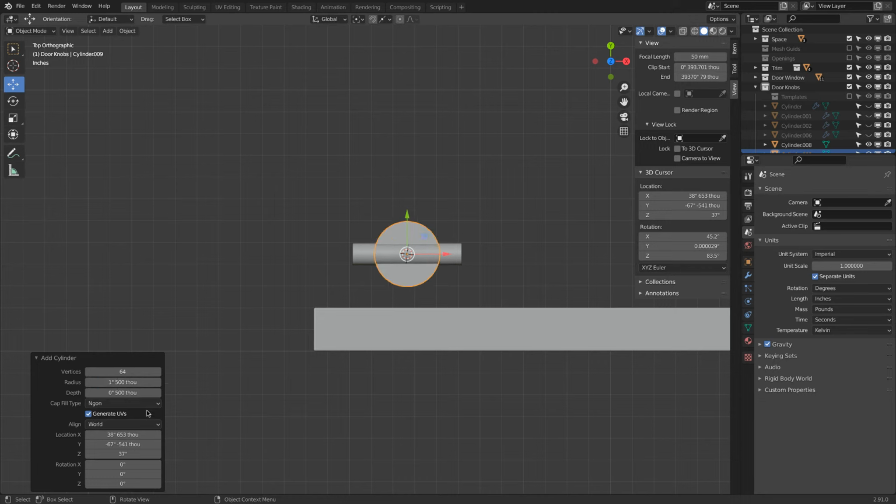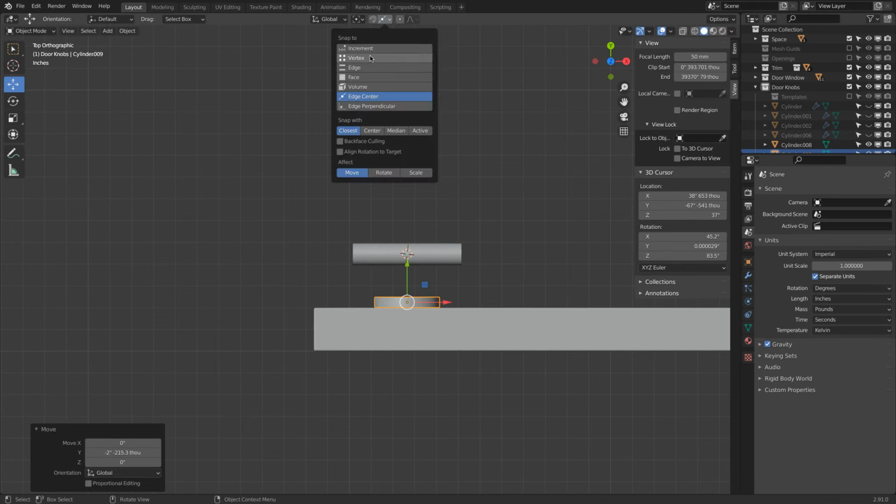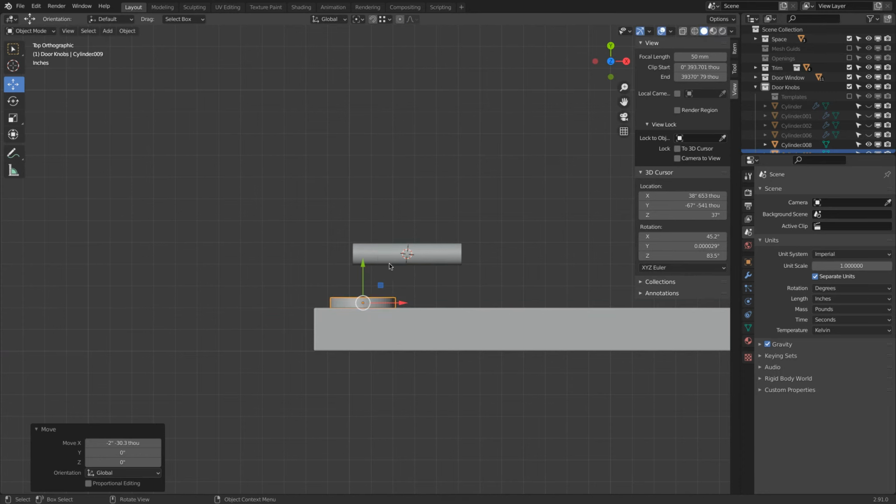And then the rotation, here we can set this as X90. Very good. Bring this down. Oh, that's the reason why my snapping was a little bit funny. You see how it snaps actually to corner points? That's the mesh the bevel modifier generates, so be careful there.